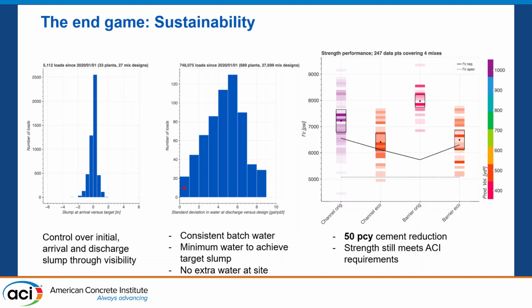So it's a wide variety, again, in how consistent they are. You can see the contractor here, this is where they lie, the very smallest part right here. So they are controlling their water as best as possible. Once they did this, they started to look at their strengths, and for some strange reason, the strengths looked really good. Not only that, but when you apply this to how you're designing your mixes with your over-design, they realized that their mixes were way over-designed.